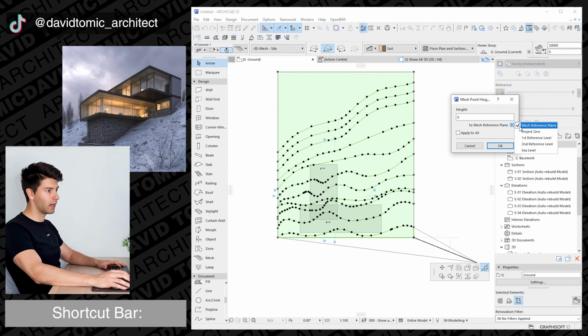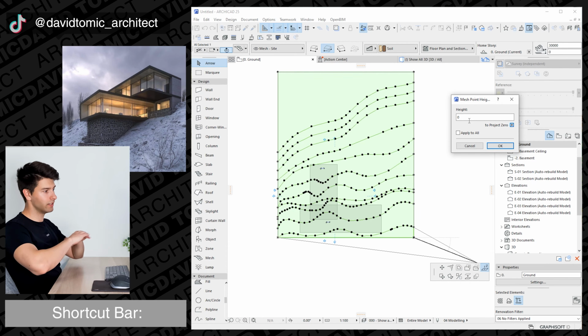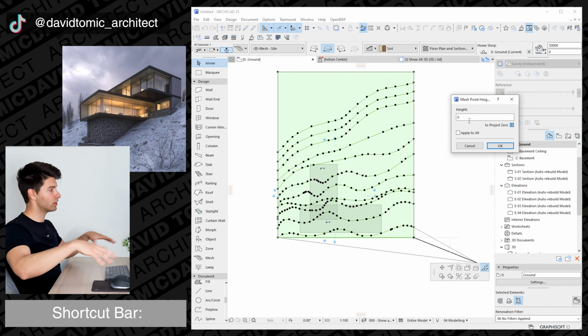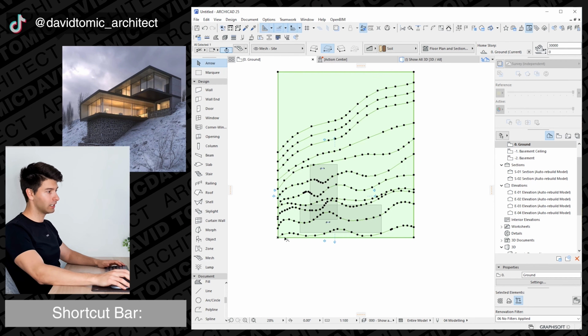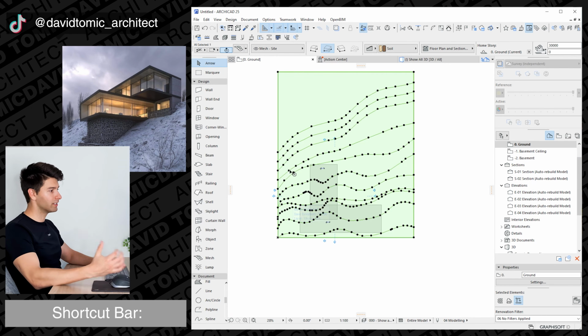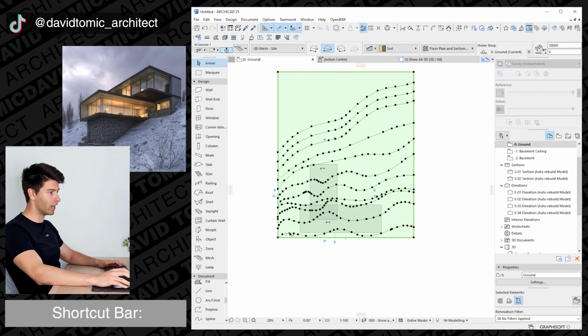So clicking on that, I'm going to change that to project 0. And that is going to be project 0, 0. So basically for me, that is the top of my boundary. That is my ground floor of where I enter, which is 0, 0. I'm going to click OK on that line. Now, because I made 9 identical lines that ended roughly at the edge of this building, I'm going to lower them by 1 meter each.